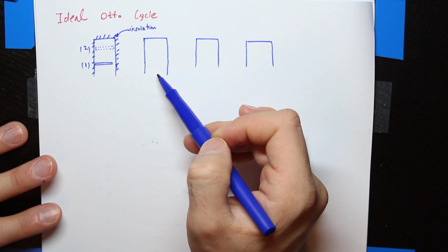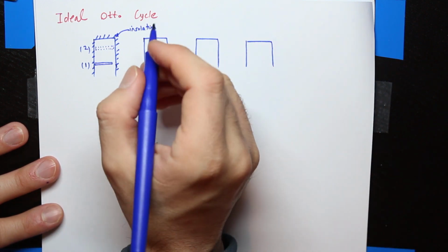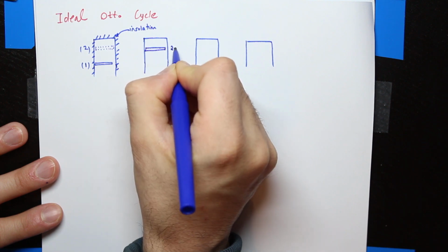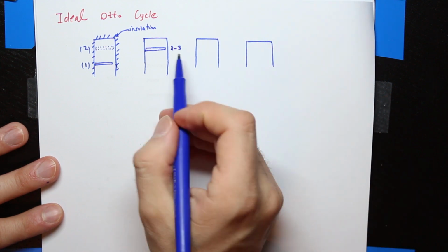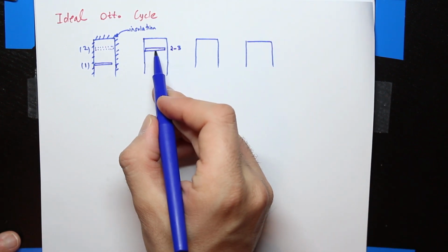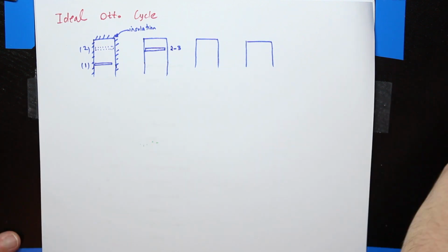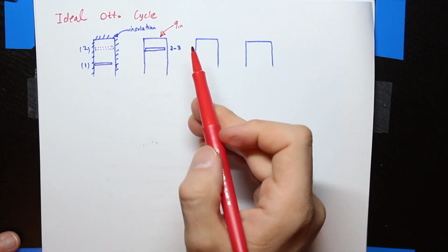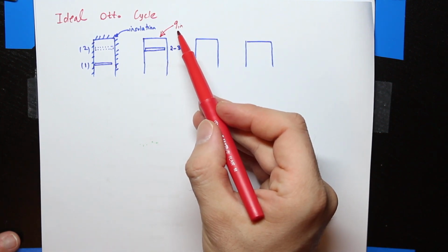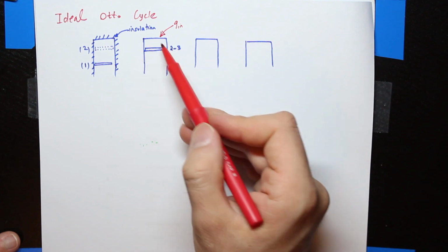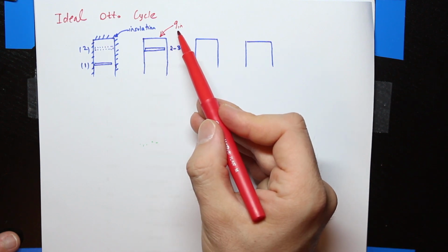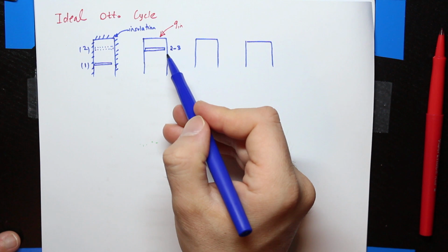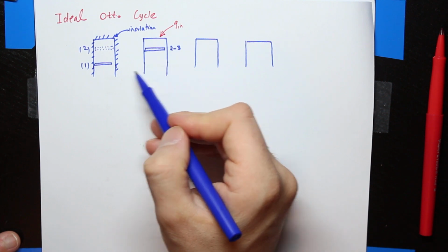Now, in the next schematic, the piston doesn't really move. It just stays at its location. It starts from state 2 and ends at state 3. So we have two different states but the location of the piston doesn't change. What happens here is the heat addition. This Q in, according to the air standard assumption, represents our combustion. Instead of discussing the chemistry of the combustion, we simply show that with a heat addition, Q in. And if you noticed, our cylinder is not insulated here, so you do not see the hatch patterns anymore.